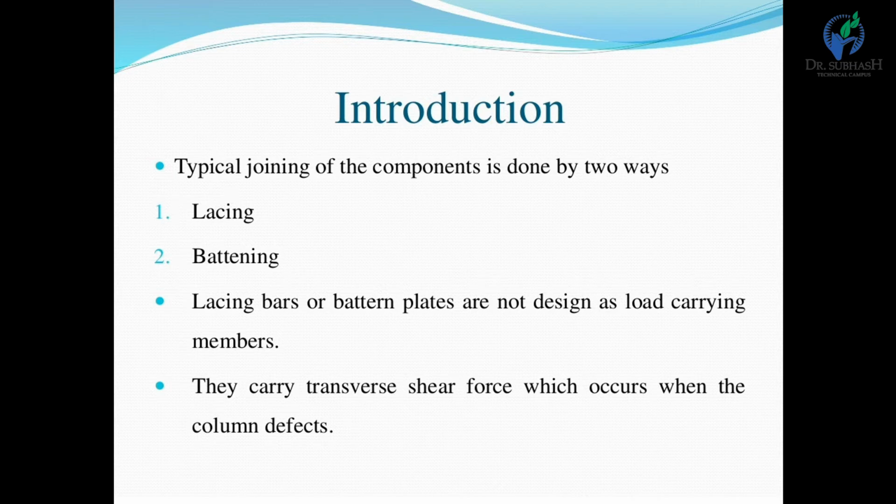Before we start lacing, we should know the function of lacing and batten plates. The function of lacing bars or batten plates is to hold the main components of the built-up section in their respective positions and to resist the stresses in them. They are not designed as load-carrying members, but are designed to resist transverse shear force that occurs due to column action.